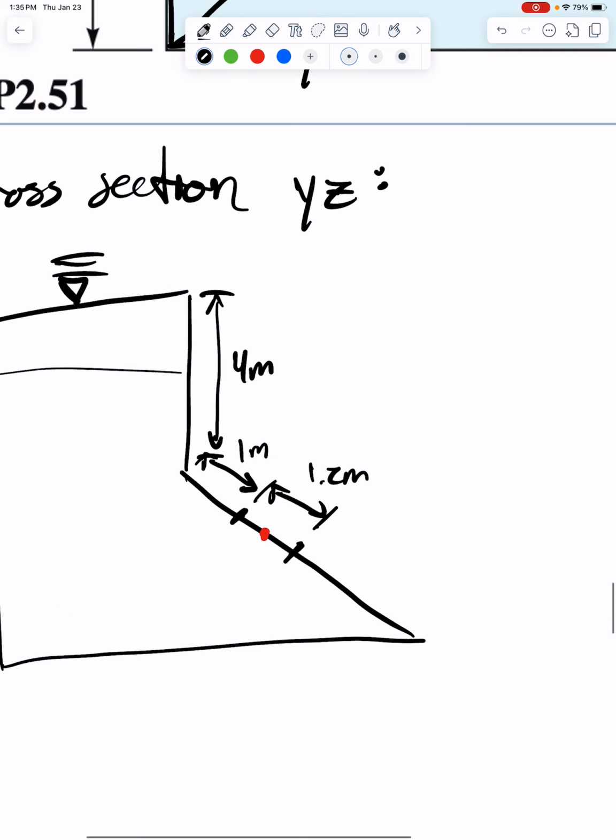So what we're missing is this y value, so we can determine the total height of the fluid column sitting above your centroid. One way we can do that is through similar triangles. We know that there's a triangle down here with an angle of 40 degrees. Therefore, through similar triangles, that angle is inherited by that red triangle that I've shown here.